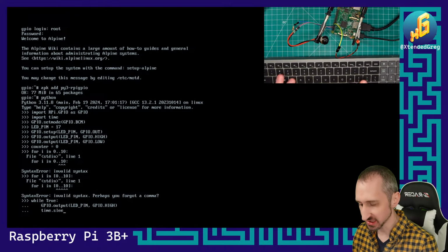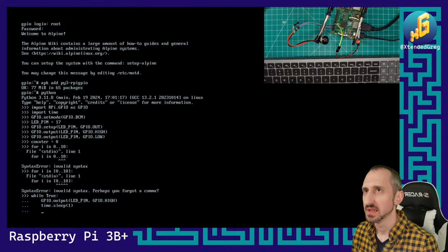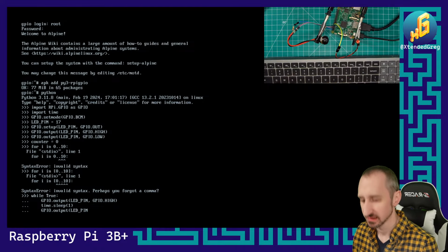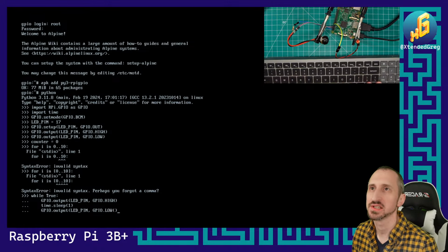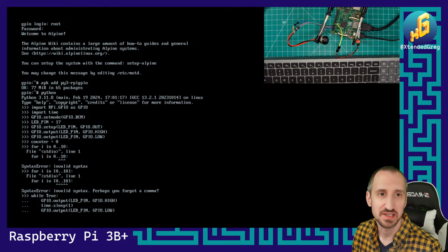So we're going to do time.sleep, and we're going to set it to 1 second. Then we'll go in again. We're going to do GPIO.output, LED pin, GPIO.low. Right, so we went high, waited a second, we went low, and now we're going to wait another second, and that'll end the loop.